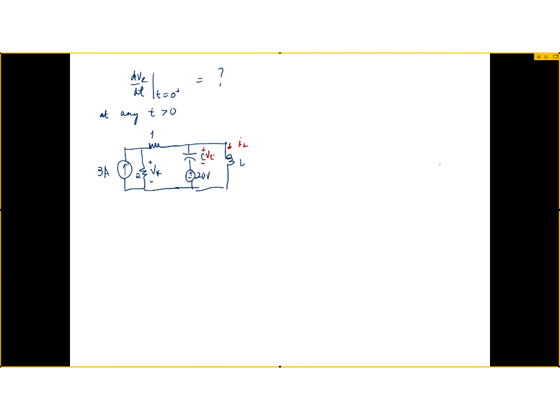Okay, any other suggestions? Okay, so we could do nodal. Is that what you're going to say? It's usually nodal, KVL, KCL, or mesh, right? I don't like the mesh because it creates new variables, right? I like nodal. Why? Because one of the variables is directly VR, right? And for the other variable here, what's the node voltage here? Is it DC?